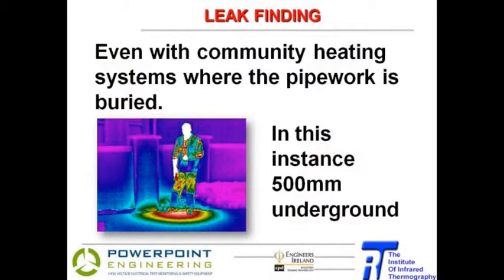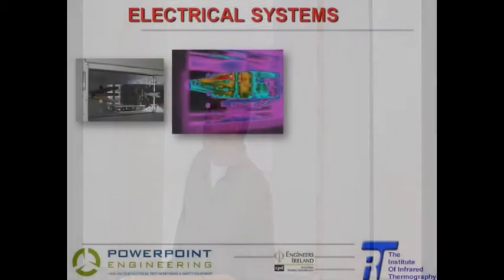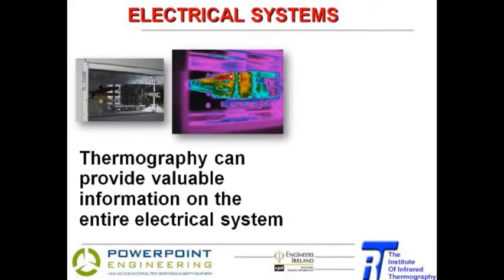Admittedly, you have to get the right conditions. You need to get the greatest amount of temperature difference. So in that instance, we put the heating system up as high as we could. And I went essentially very early in the morning. Building thermography is a bit of an antisocial occupation, because typically you're working when it's cold outside and you're outside. You want a good temperature difference. So you want the building, the structure to be heated, and you want a low temperature outside to maximize the temperature difference. But very effective.